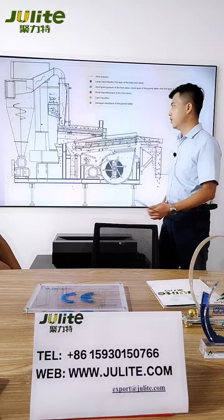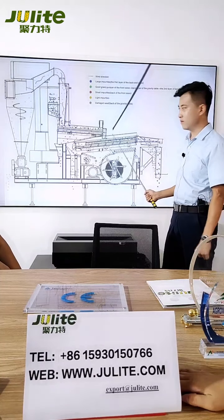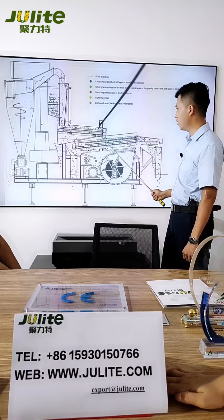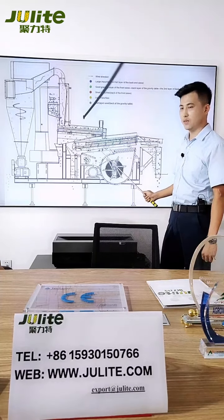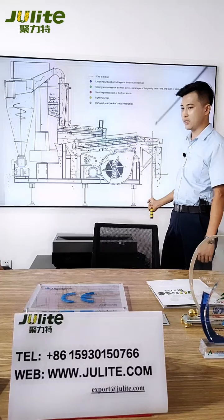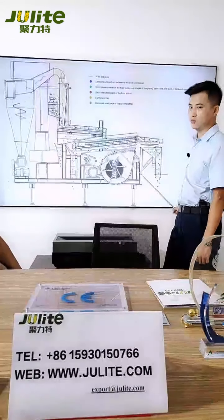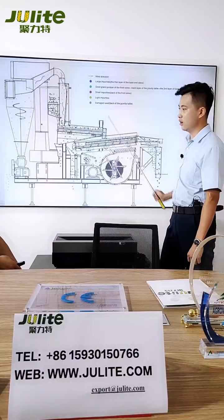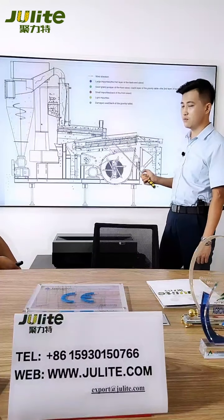Yes. So after the materials go into the gravity table, the heavy and the light impurities will go down to the back, and the fine materials will go to the outlet and be discharged by here. And these are blowers to blow the air from the bottom to the top, and this is the whole flow structure for the materials in these machines.